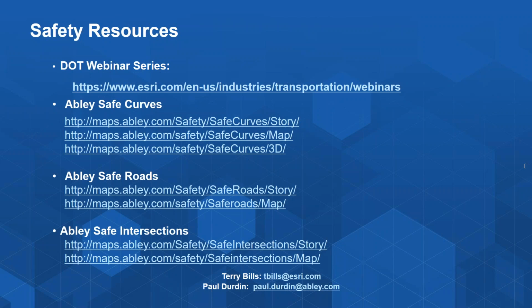Okay. And another question, is there a minimum point per meter for the LiDAR? I don't know if... Yes, I can answer that. The digital surface model files that we procured from the government source LINZ for this had basically a sampling frequency of each pixel on the raster surface tile equal to 1 meter. So that would be a sensible minimum for looking at it in plan view.